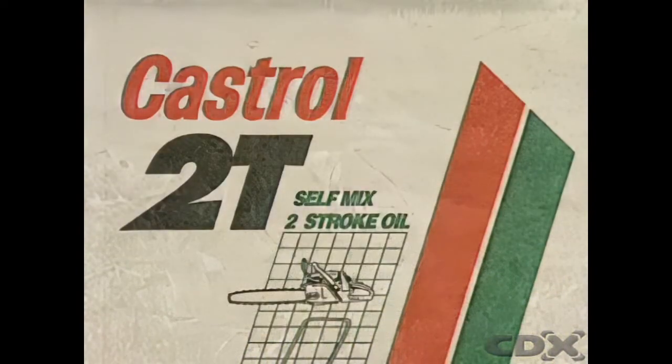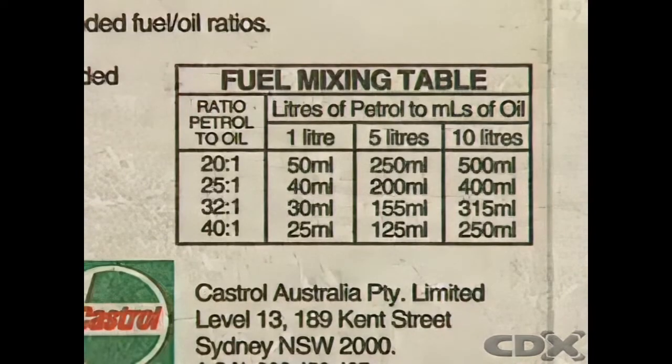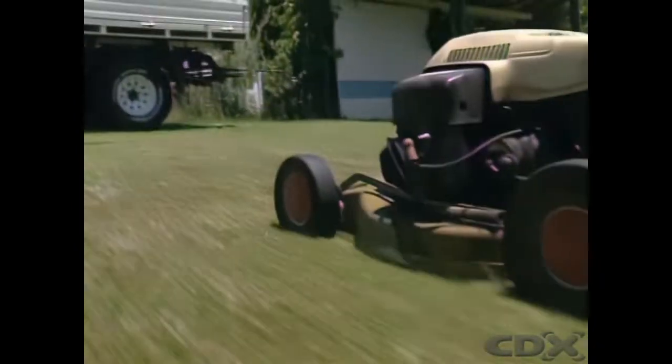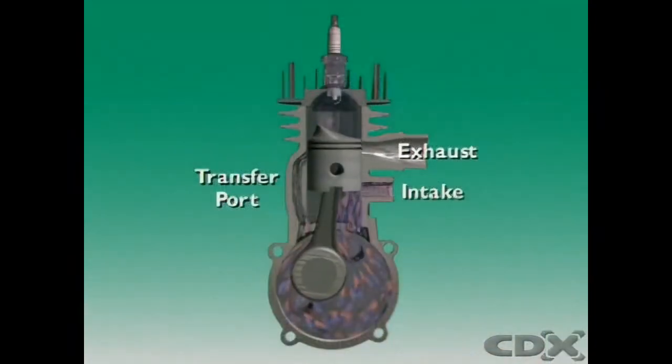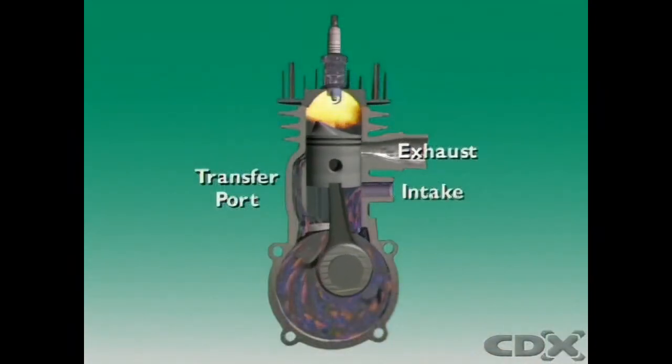Most two-stroke gasoline engines use a set gasoline-oil mixture for lubrication. There are different kinds of oils and gasoline oil mixtures. They must be used according to the manufacturer's specifications. For small two-stroke engines, the oil and fuel are pre-mixed.